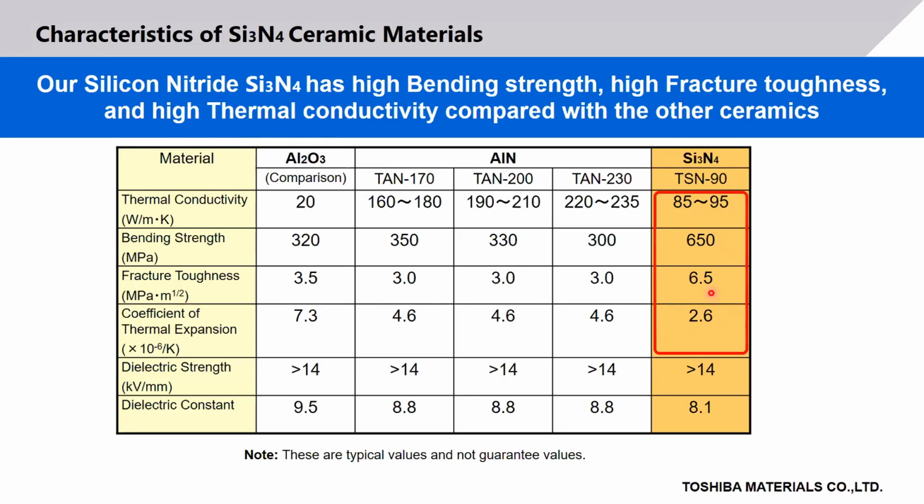Another very important parameter is the coefficient of thermal expansion. It's 2.6, very similar to silicon. So during thermal cycling, during temperature variations, they expand linearly at the same rate. So there is a much lower risk of malfunction.